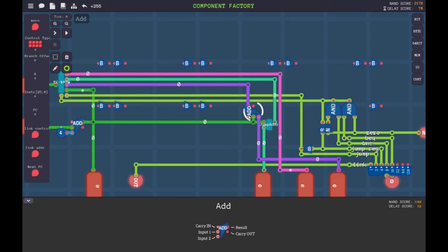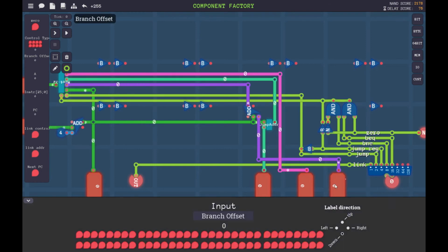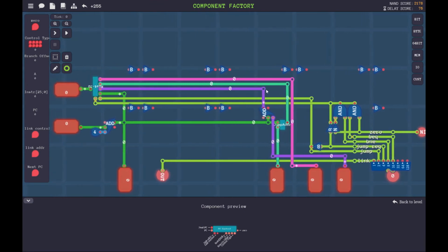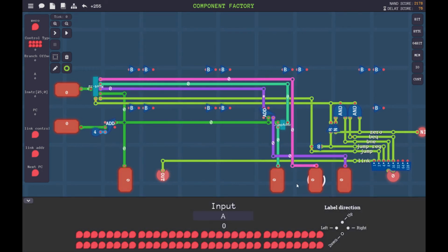This adder takes the address of the instruction following the current one, and it takes the branch offset, and it just adds them. And if we are supposed to do a taken branch, which remember was option number 1, as in the one labeled 1, then we use this value. The jump address that we calculated is going to the option labeled 2, and the option labeled 3 is coming straight from the ALU-A input, which is coming off the register file's read-A output. So this one's for jump register.